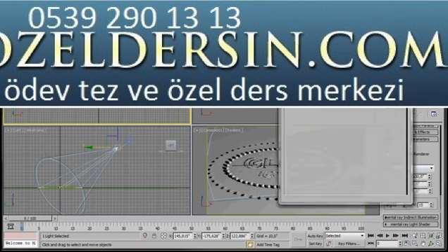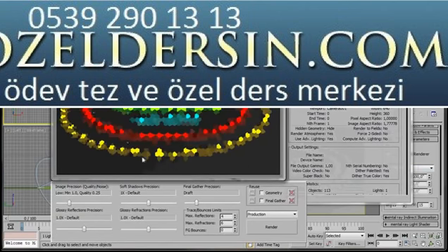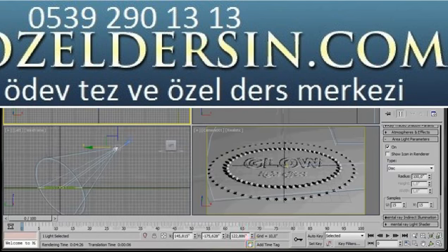Let's go to the main toolbar now and click on the render icon. I'm going to turn the video off while this is rendering. Wow, that is effective. Let's add one more final touch to the spheres. Let's close the renderer and we'll come back over here to the area light parameters. And in the radius, I'm going to boost that up to 130.